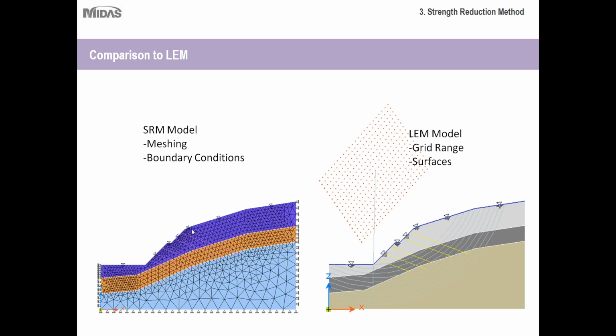The reason this is done is because the smaller your elements are, the more refined or the more detailed your analysis is. So naturally, you'd want your elements to be smaller, or you'd want the analysis to be more detailed around the areas where you'd expect more amounts of deformation or more strain, etc. As you go closer to where that strain or that deformation occurs, the elements get smaller. Whereas if you go to the edges over here, or these areas, you're not going to experience much deformation or strain at all, so the elements can be much bigger.